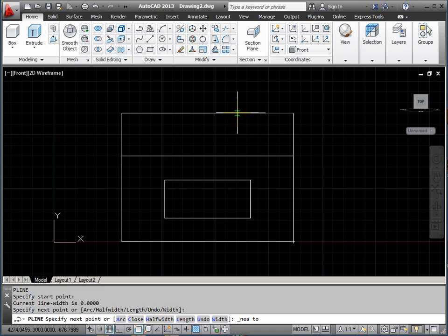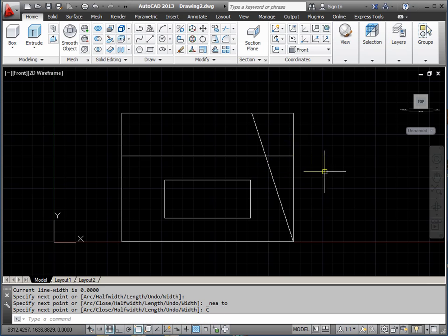Okay, this is just a sketch. Just want to make sure that I don't go too far, or I might slice off the window. So I'm not going to go too far along. About there, kind of roughly in line with the window should do. Okay, then press the letter C to close the shape. So C and return.